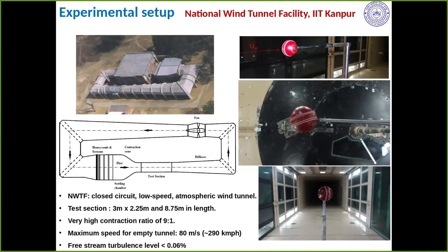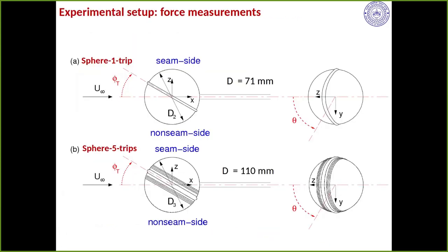This is a wind tunnel we had. We took a ball, put it on the sting, no rotation on it. That's a model simplification. We can change the seam orientation by taking different models and putting them on the sting. We can change the flow speed in the wind tunnel. We soon realized that repeatability is a problem because these balls are handmade, so no two balls are identical. So how do you trust your experiments? So we 3D printed them.